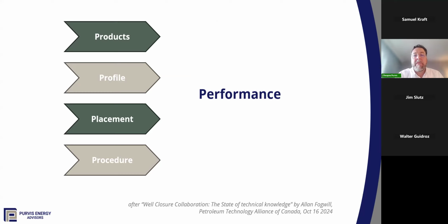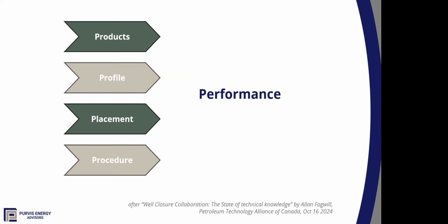But more importantly, when it comes to shale reservoirs, we know, as a matter of reservoir engineering, that the wells will repressurize over the lifespan of the plug. We're only taking out between 5 and 15, maybe 20% of the fluid in place in some cases, and therefore, as a rule of thumb, it will eventually, over decades, but within the lifespan of my children, within the lifespan of the plug, repressurize to 80, 90, 95% of its initial pressure.